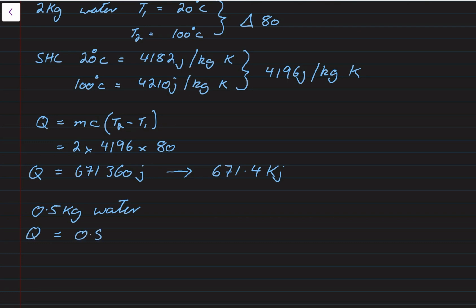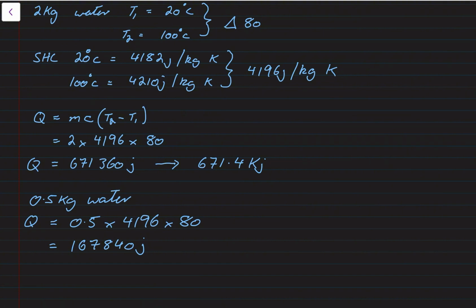So 0.5 times 4,196 times 80 degrees. That equals 167,840 joules of energy. So we can see there that the energy transfer is directly proportional to the mass.